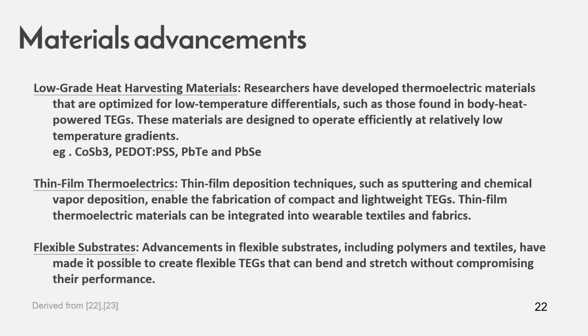And coming on to the third advancement is low-grade heat harvesting materials. Researchers have developed thermoelectric materials that are optimized for low temperature differences, such as those found in body heat powered TGs. These materials are designed to operate efficiently at relatively low temperature gradients. Some of the examples are CoSb3, PEDOT:PSS, that's an organic compound, PbTe, and PbSe.